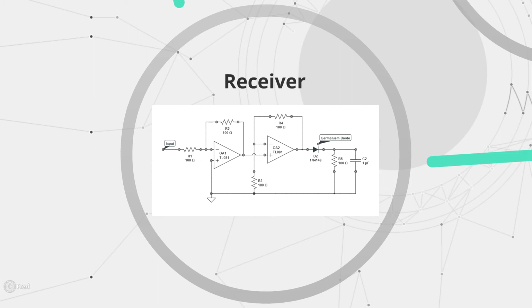For this project, we decided to utilize a simple design passive rectifier that results in less potential errors. The signal is amplified, with the voltage and current amplified separately, and then fed into the rectifier part of the circuit that consists of a germanium diode to convert the signal to a positive going waveform. The wave is then bypassed into a resistor and capacitor in parallel configuration, which converts it into a digital waveform needed for the measuring device.